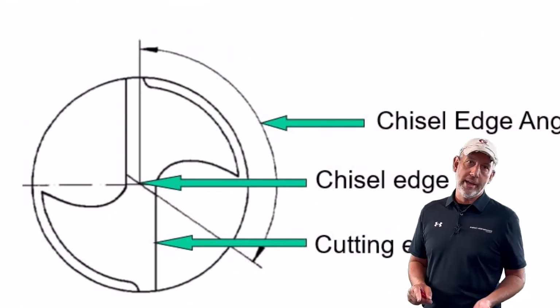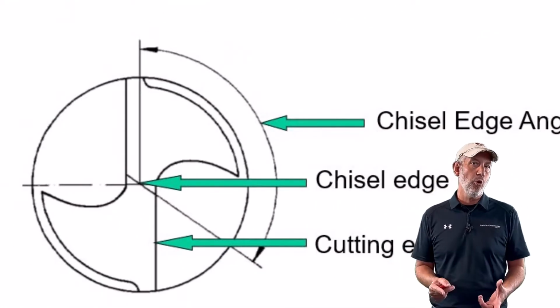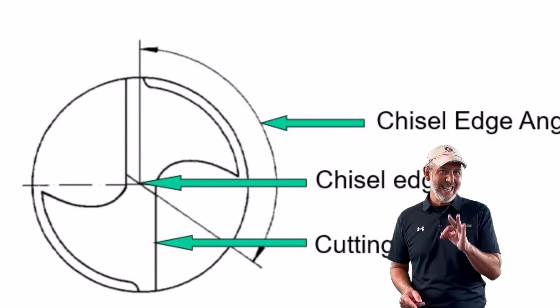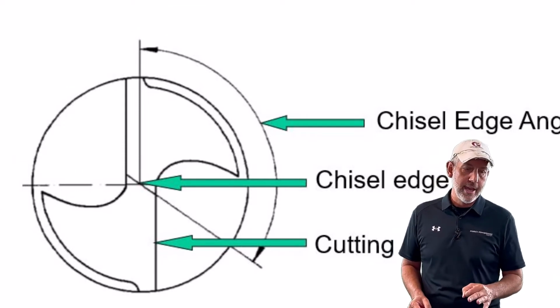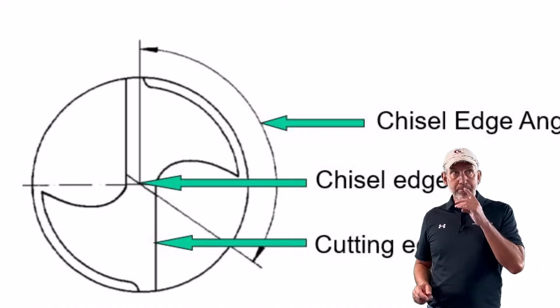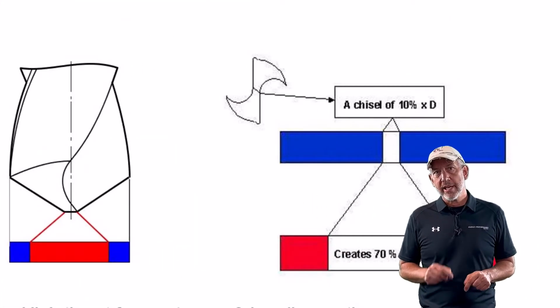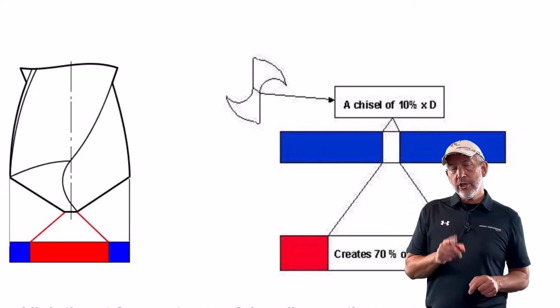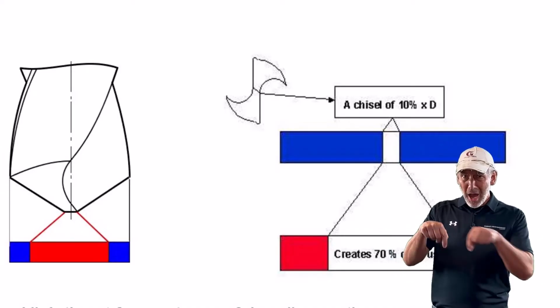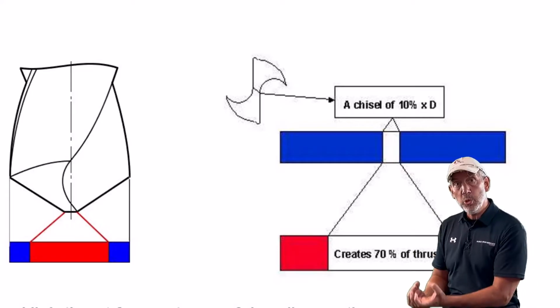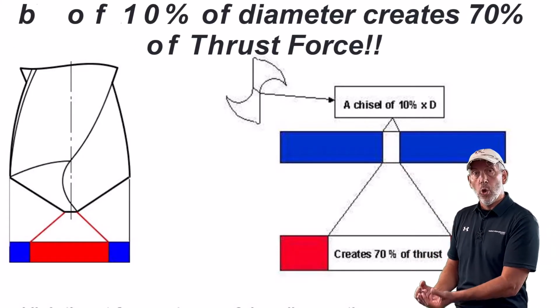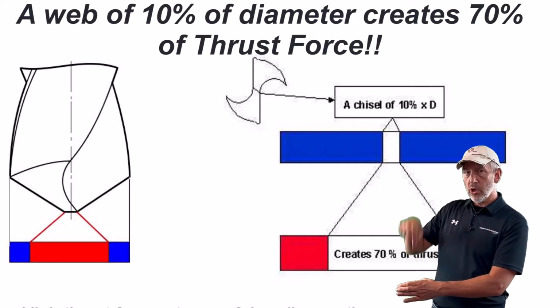So let's just talk about a drill point really quick before we dive into high-performance carbide drills and getting the best quality hole that you can. A drill point really is creating all your force. What that point looks like on a drill is really going to determine how much pressure is pushing up on your whole system, because it's all axial force.